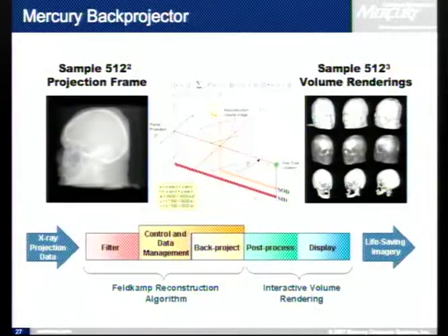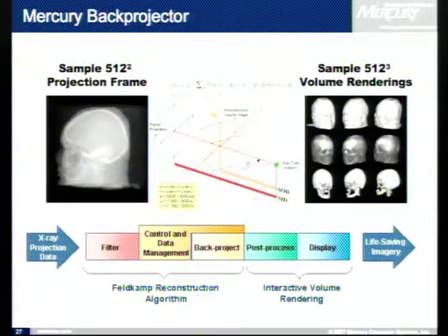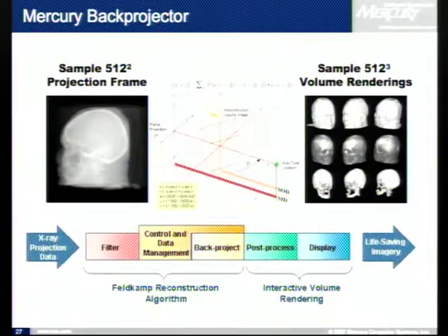So the operation is essentially a vector matrix multiply. For the FPGA, there are many aspects to the entire rendering pipeline, but the heavy lifting, the inner loop that really needed acceleration for back projection, was the vector matrix multiply inside the inner loop. And again, suspiciously, so many things in most people's careers seem to repeat over and over.